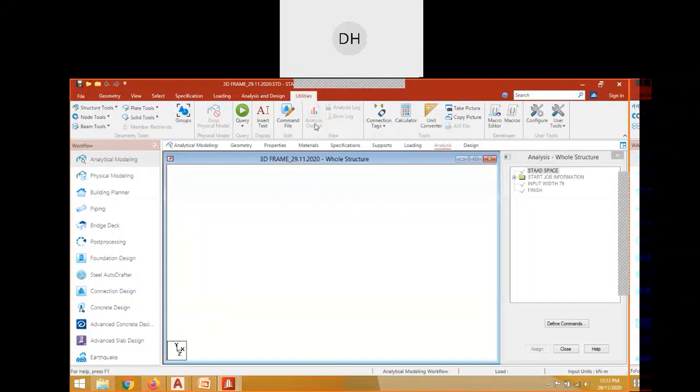For example, the floor load transmission, because we are assuming two-way load transmission, and sometimes if the panel dimension is like one way, there you can have two options. Either you go with the two-way thing, it does not make much difference. Even if you go with the two-way thing, the load will always be there on the shorter sides, but of course the load transferred to the shorter side is very, very less. So that may give you a warning that the floor load generation has a one way or two way definition. There you have to check whether this warning is relevant to you or not.